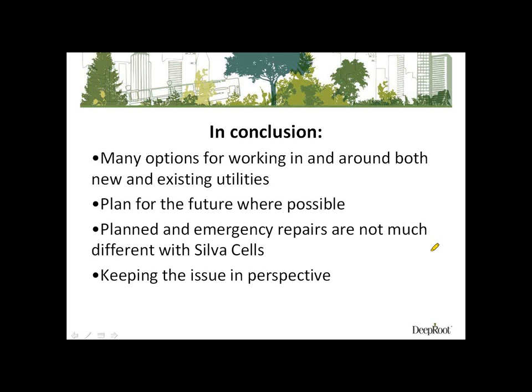We tell people as a rule of thumb that each Silva Cell, which is 10 cubic feet of soil, can hold about 2 cubic feet of water. So approximately 20% of the system can be used for storage in a stormwater application. And that's a pretty conservative number because it's going to depend on the mix you choose, and it also doesn't take into account interception by the tree or evapotranspiration.